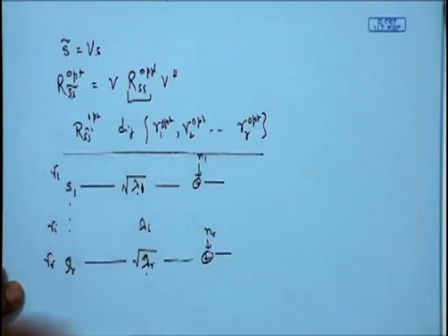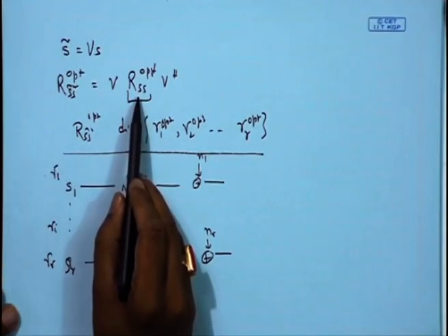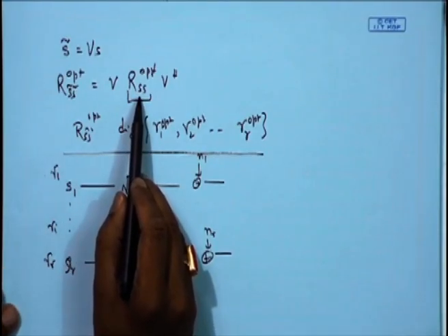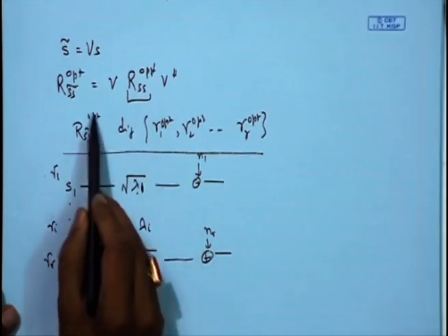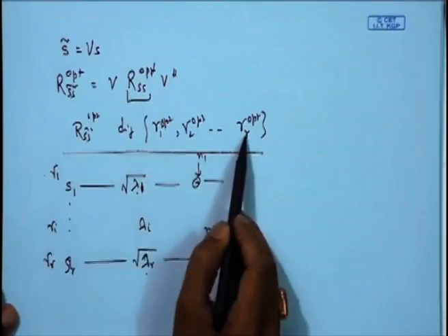So, this is what is finally radiated, although RSS is identity, although this is an R cross R diagonal matrix because the S are all independent. However, what is actually radiated has this kind of power. So, if you can allocate power in proportion to the channel strength, we can achieve the maximum value of capacity when channel state information is available at the transmitter. On the other hand, when channel state information is not available at the transmitter, the best you can do is to provide equal power and leave the covariance matrix of the transmitted signals to be the identity matrix.